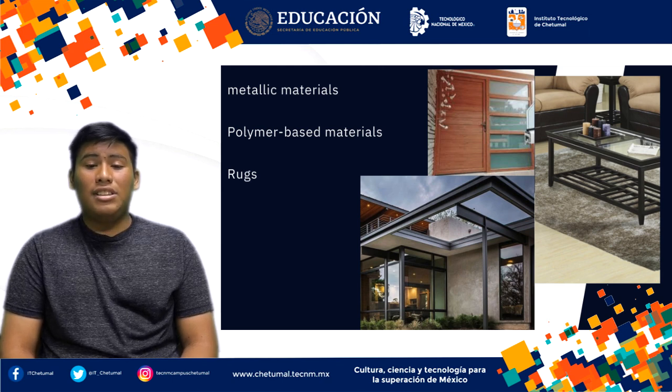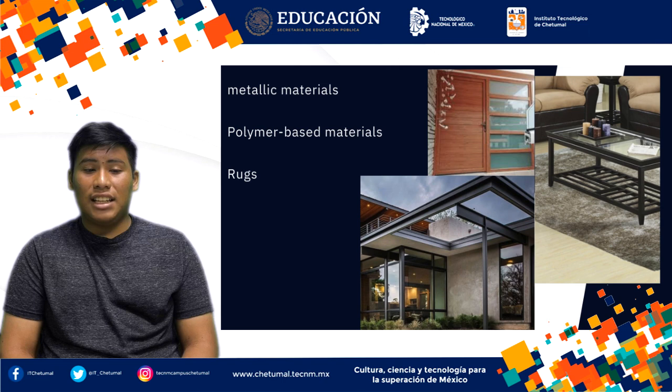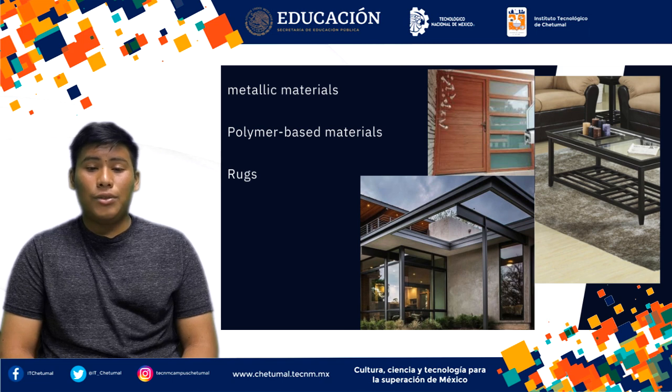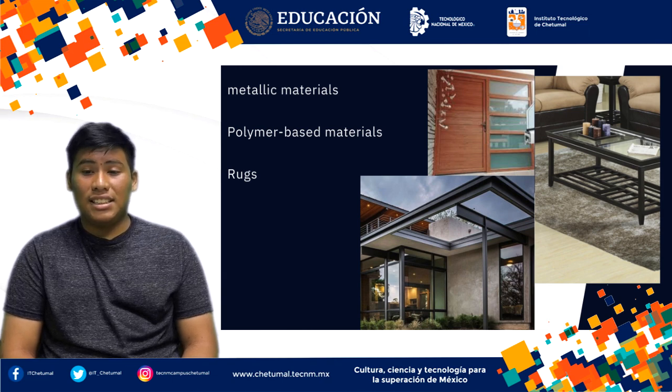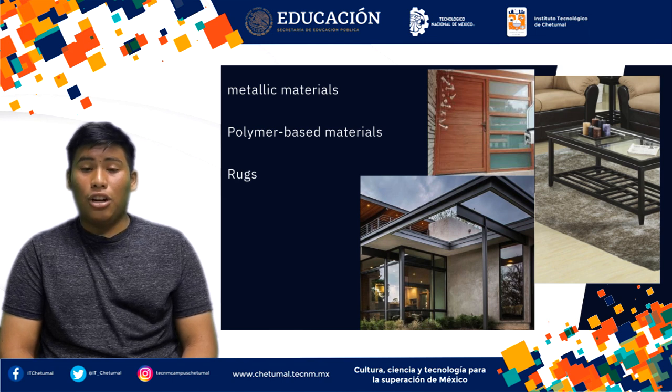Polymer-based materials are increasingly used due to their versatility and their low cost. The types of polymers: PVC, which is used in coatings, ceilings, and decorative panels. You have polycarbonate, transparent and lightweight, ideal for roofs and windows. Next, you have the epoxy resins. They are used in industrial and decorative floors for their resistance and easy cleaning. The installation of these materials is often preferred for their low maintenance and their great durability.